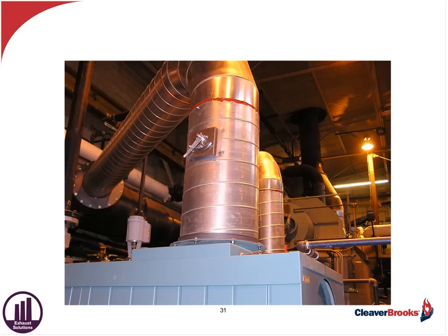And so what I've got is a mechanical damper here that I can set, so I know that when I modulate that burner from low to high fire, I've got just the amount of resistance. Either I increase the resistance or I decrease the resistance to be able to handle that particular draft situation throughout the firing rate during that season.